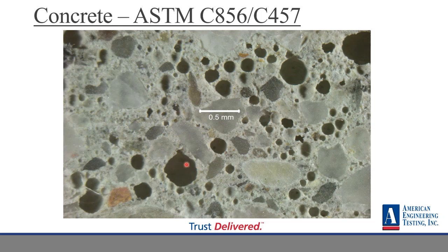But with this method, we also look for any microcracks that might be in there. We can see different secondary deposits that might affect concrete durability. I'll talk about alkali-silica reactivity in a second, and we can see that in the concrete as well.